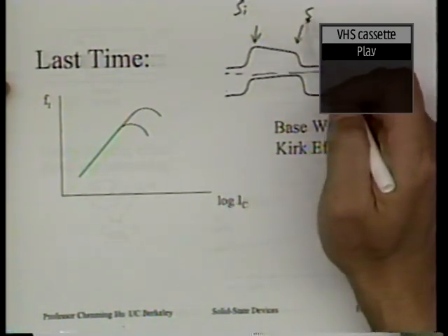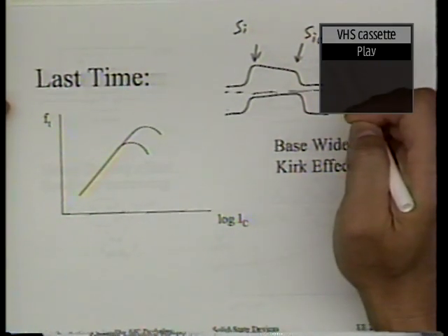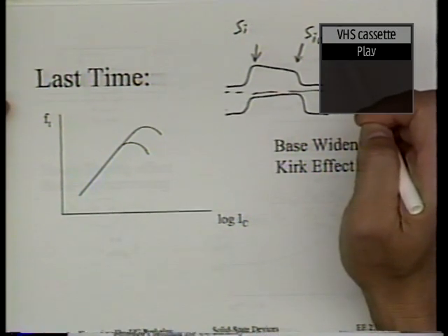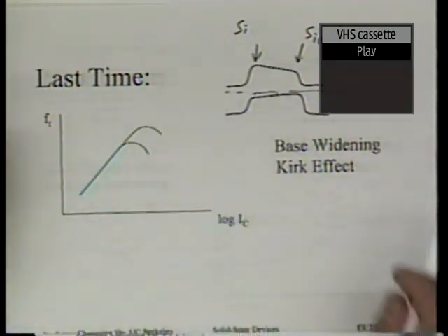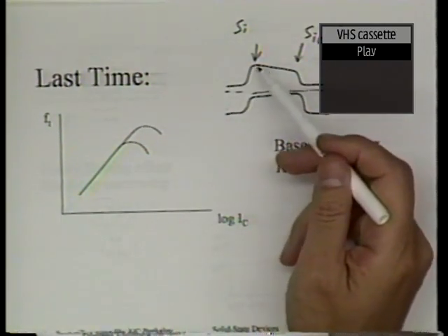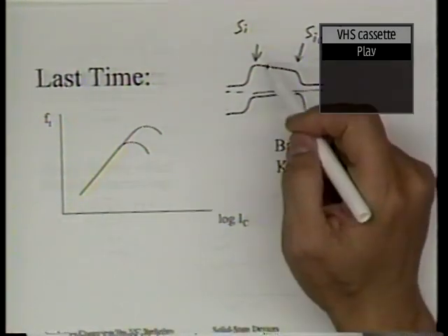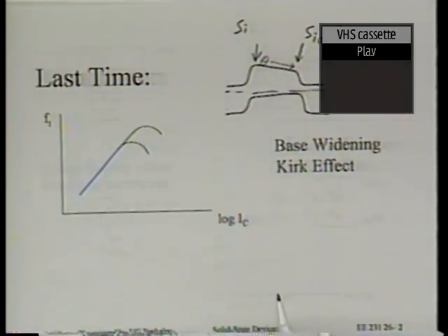At this point, maybe silicon is 0.9 or 0.85. Actually, 10% germanium is about all that it takes, so germanium is 0.1, all right? With this more or less linear gradient, you end up with a slope in the conduction band edge, and that is an electric field. Any electron in the conduction band will just be pushed away, or drift, toward the collector, and this gives silicon germanium superior speed.